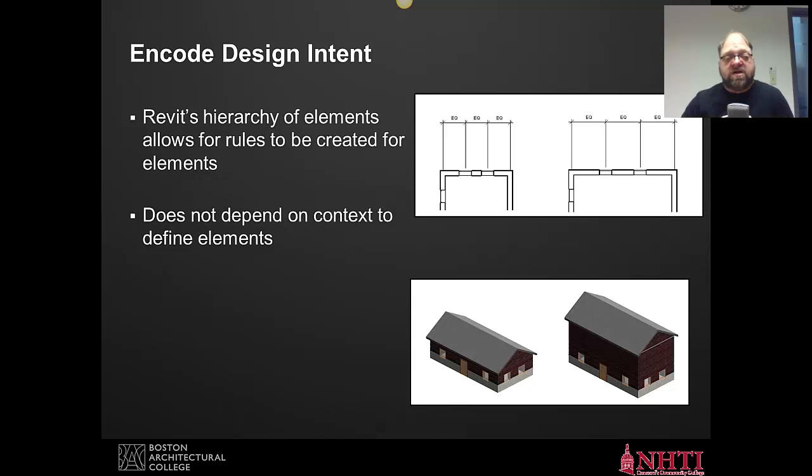So for example, when the roof is placed over the top of these 4 walls in the second image here, the walls automatically know, or they will ask you, I see that you placed a roof above me, above these walls that you drew. Normally, walls go up and touch roofs. Should I make that happen? So there's an example where Revit is trying to figure out what your intent was. Does every time a roof appears above a wall, does it attach?